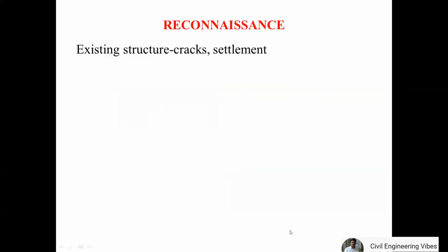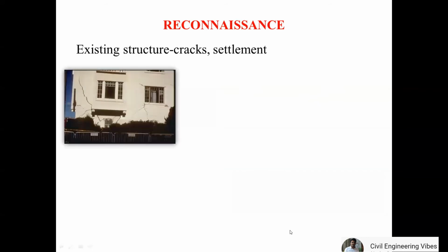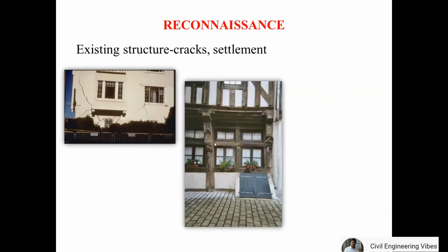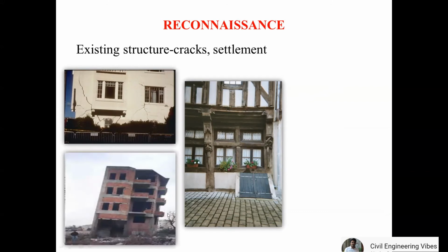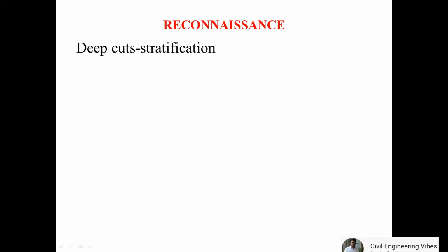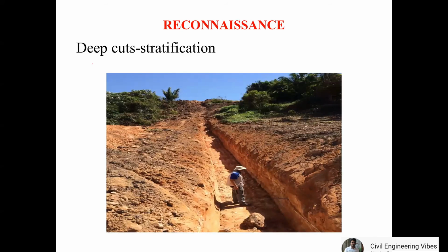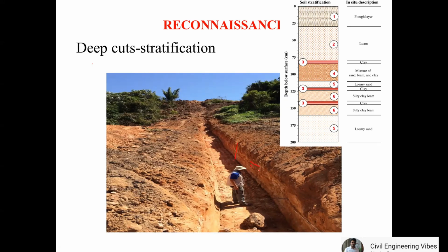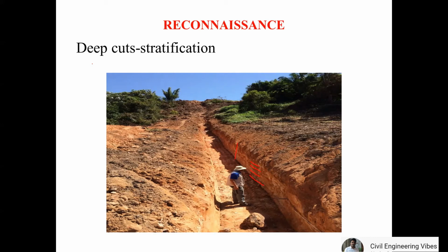Next, observation of the existing structures around the site. If cracks are formed from the bottom of the structure, then it is because of the foundation or subsurface, and the settlement of the structure is easily judgeable. Then it means the rate of consolidation is on the higher side, or chemical weathering is happening. Now coming to observing deep cuts. If it is homogeneous, then no worries, bearing capacity is fair enough. If layers or strata of the soil deposits are observed, then investigation is necessary.